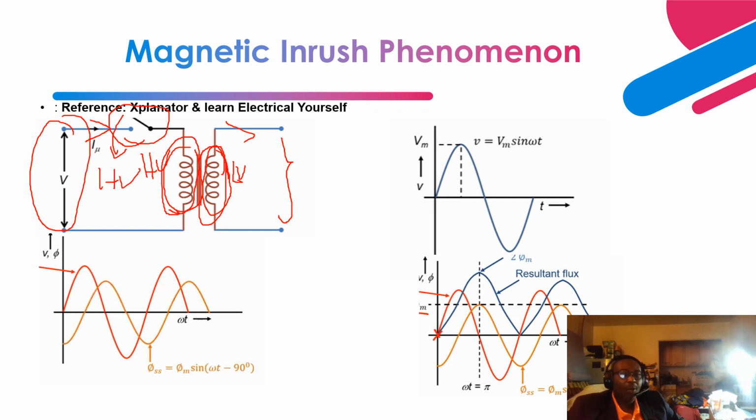So the differential relay is going to see it as a differential current, and will provide a trip signal based on that if you don't have the right relay settings in place to inhibit the components of this inrush current that is flowing.